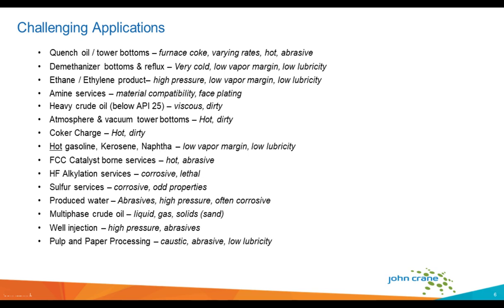Heavy crude oil, atmosphere, vacuum tower bottoms, or coker charge pumps, going down to, let's say, HF acid in the alkylation services, where it's very corrosive and lethal when it comes in contact with humans. Sulfur services, corrosive, and it has a very odd property when it comes to viscosity, whereas viscosity can swing quite rapidly with minimum temperature change. Produced waters normally is abrasive and high pressure and often corrosive. And well injection is also high pressure and abrasive, and pulp and paper process where it's caustic and abrasive and low lubricity.